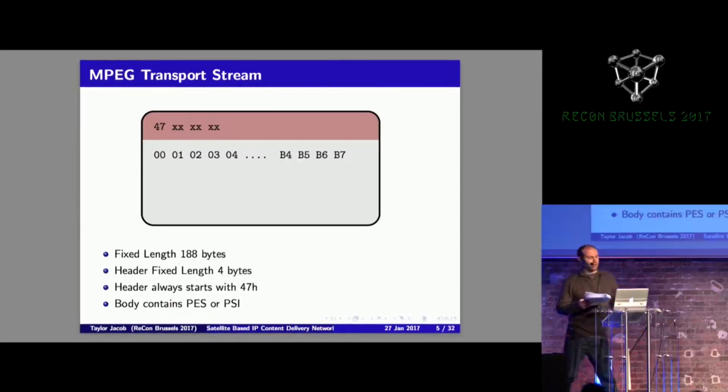And the standard way this data is moved is MPEG transport stream, also called TS for short. And the format's relatively simple. It's 188 byte packets that have a simple 4-byte header. And all you really need to know for this presentation is that it starts with 47 hex, and there's a 13-bit field called the packet identifier, more commonly known as the PID. So on the transport stream, there's 8,191 available PIDs, and of all of them, only a fraction will be used simultaneously.